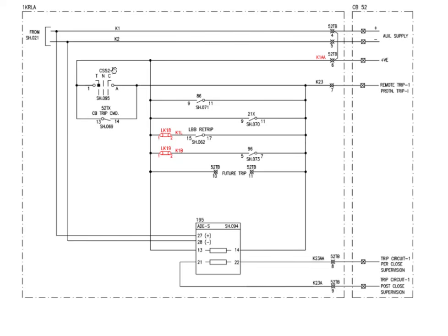Okay, so we'll need to give a DC to the circuit breaker. There are two sources of DC coming from the panel, so DC1 and DC2. The first one is DC K1 positive and the second is negative K2. And the TB number in the relay panel. So this is the relay panel.